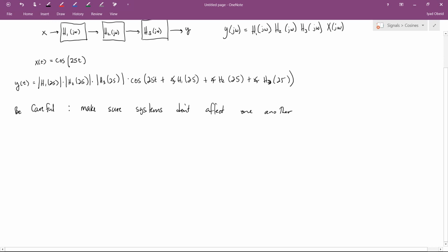Let's take a very simple system. What could be any simpler than a voltage divider? So here's a voltage divider, and let's say we make them both 1K resistors. We could think of this as a system, which I'll call H1, and there's no frequency dependency here. We can just read right off the numbers that it has a constant gain of 1/2. Now let's have another system, with slightly different resistor values: 1K and 2K. This is also a system which doesn't depend on frequency. It has a constant gain of 2/3.